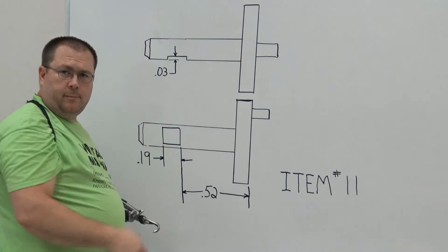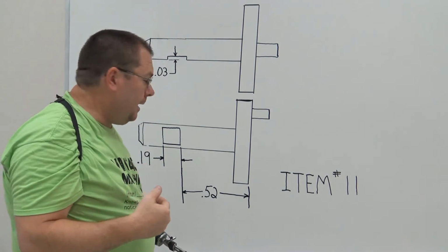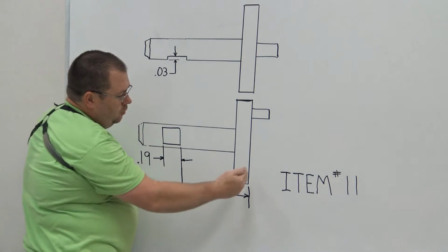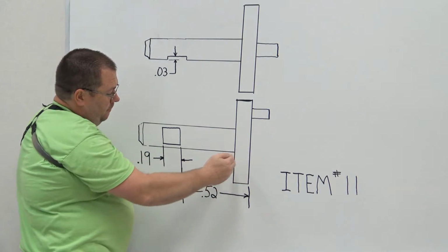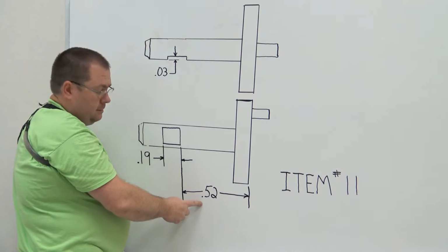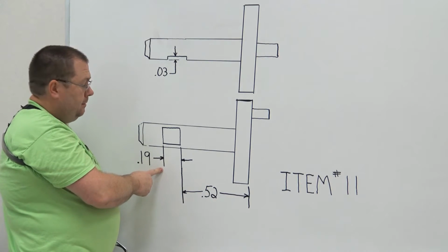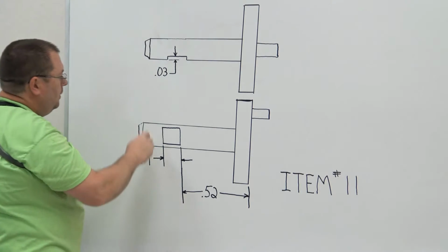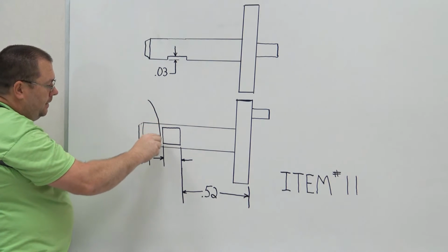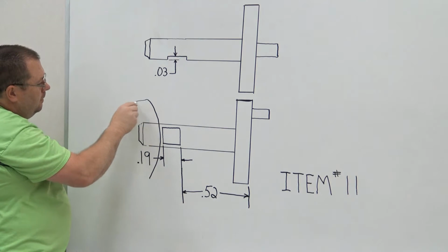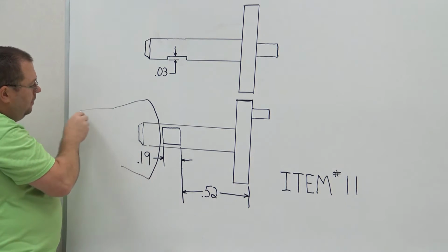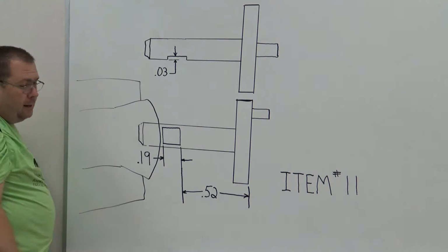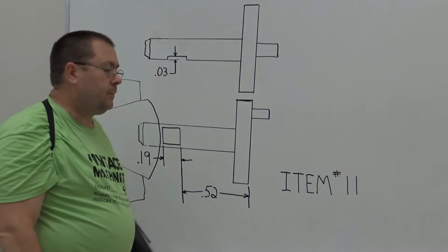So you just want to think about a collet holding on to this end. Well, because you don't want to machine into the face of Mr. Bryant's collet, what do I want to make sure of? I want to make sure that I have 520 thousandths plus 190 sticking out of the face of the collet, right? So the collet looks something like this. It's tapered back here, and it's in this square block. That square block allows us to hold it in a vise, okay?